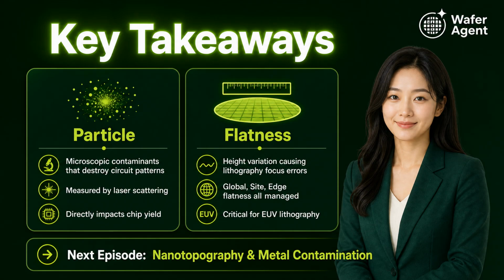In summary, particle is a microscopic contaminant that can destroy circuit patterns and reduce chip yield. It is measured using laser light scattering techniques. Flatness determines whether lithography can focus accurately. Global, site, and edge flatness are all managed, and requirements grow stricter as nodes shrink. Both parameters are invisible to the naked eye, yet they directly determine whether a chip lives or dies.